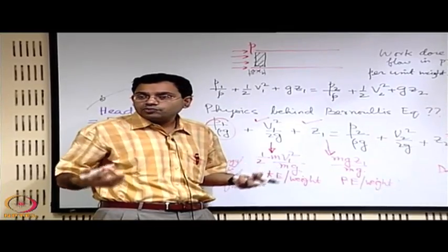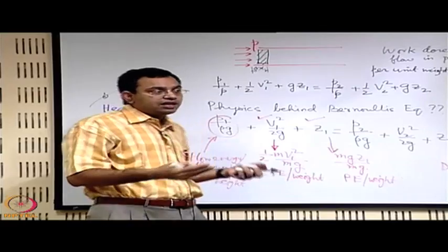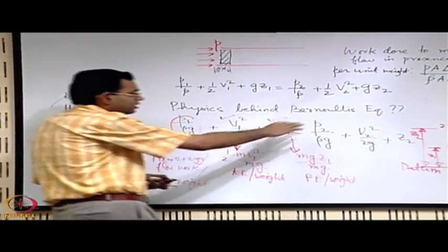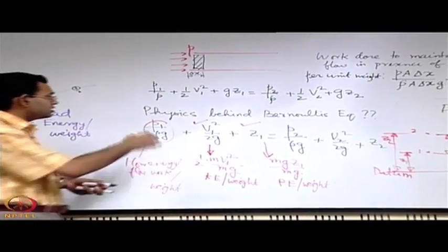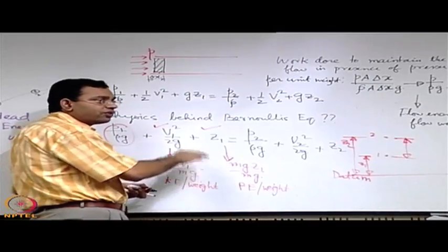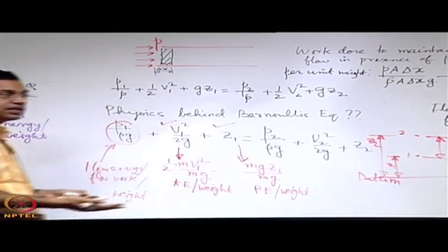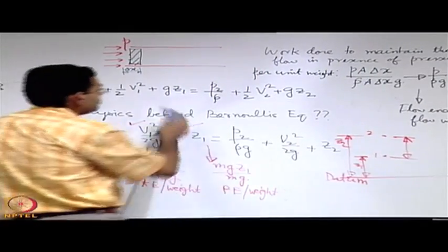If we prescribe with reference to the atmospheric pressure, we call it a gauge pressure. So you can as well prescribe the pressures in the different terms in terms of a reference pressure, and then you can substitute as gauge pressure. Important thing is whatever reference you use for postulating the different terms, it should be same in the left hand side and right hand side, that is a very common and obvious conclusion.